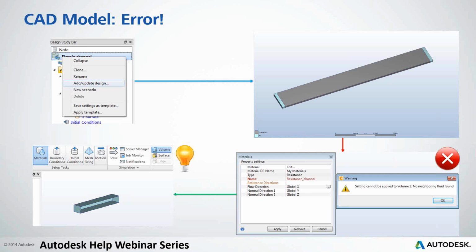I was like, why? I've just created two air caps. It should work. Why are you saying that you don't have neighboring fluids? And then when I investigated my air caps, I just recognized that I should have made an extrusion, not create a plane, and that's all. That means that when I import the geometry to CFD, it took only the surfaces and defined them as volume. It didn't automatically make a volume inside.